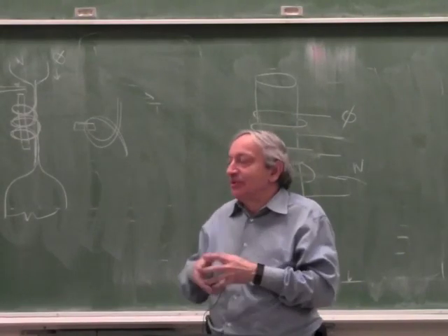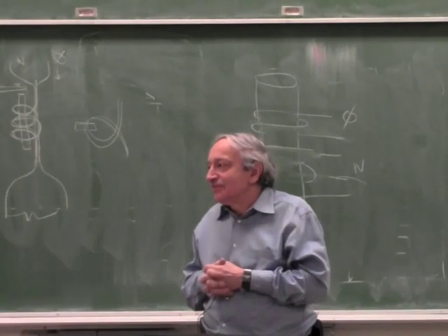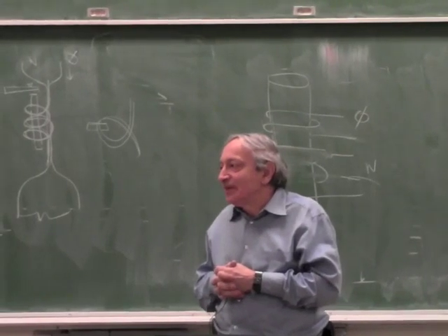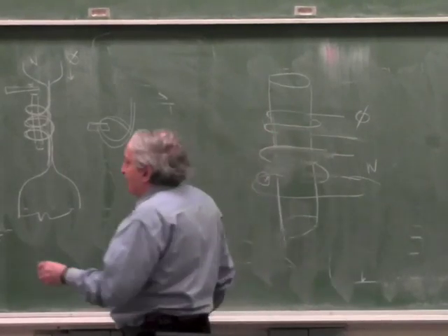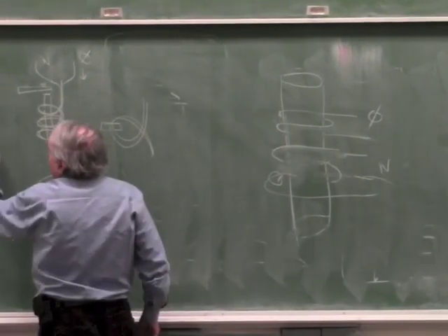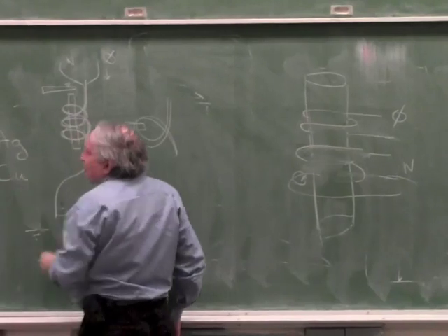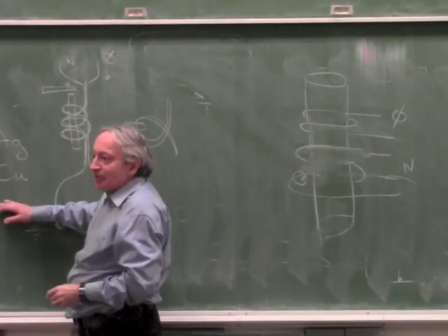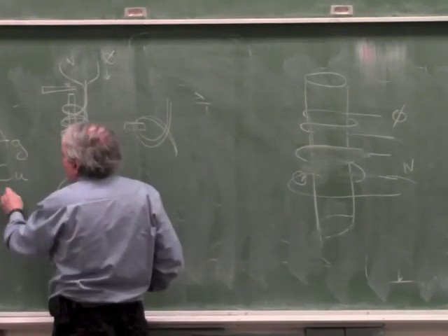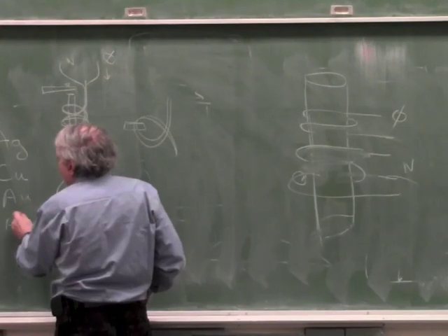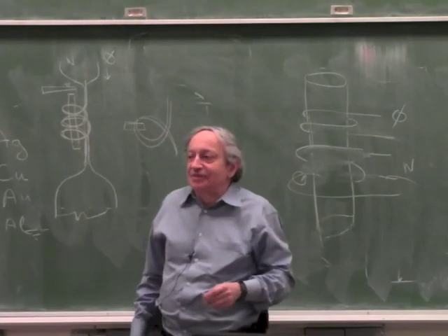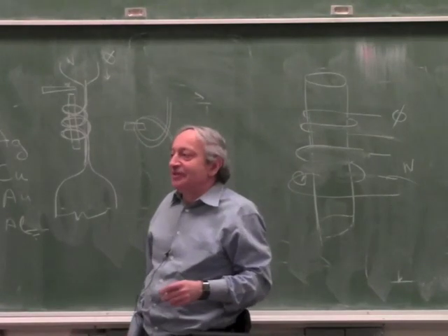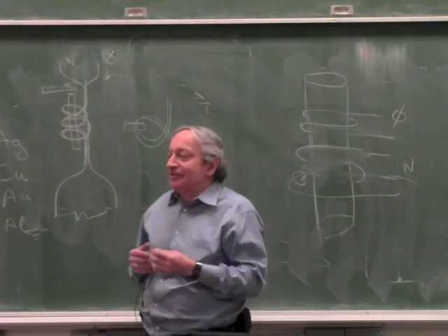What's reason number two? Does gold have a much lower resistance than copper? No, gold actually is a poorer conductor than copper, because the best conductor is silver, the next best conductor is copper, and gold is below copper. So roughly, it will be gold, and then aluminum, say. But gold has some very unique property as a connector.